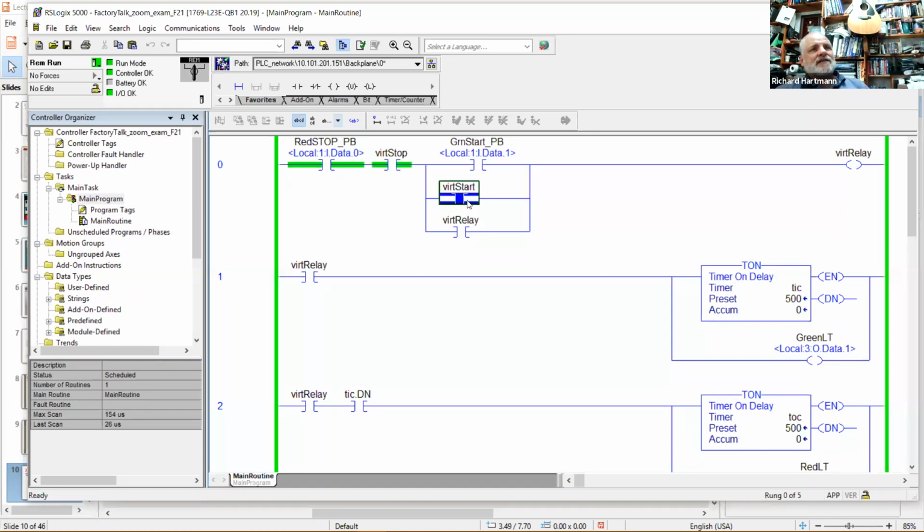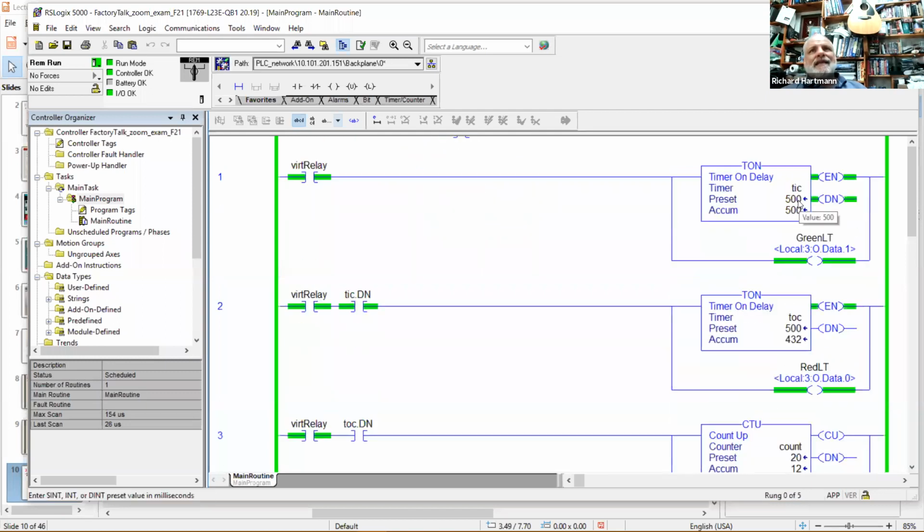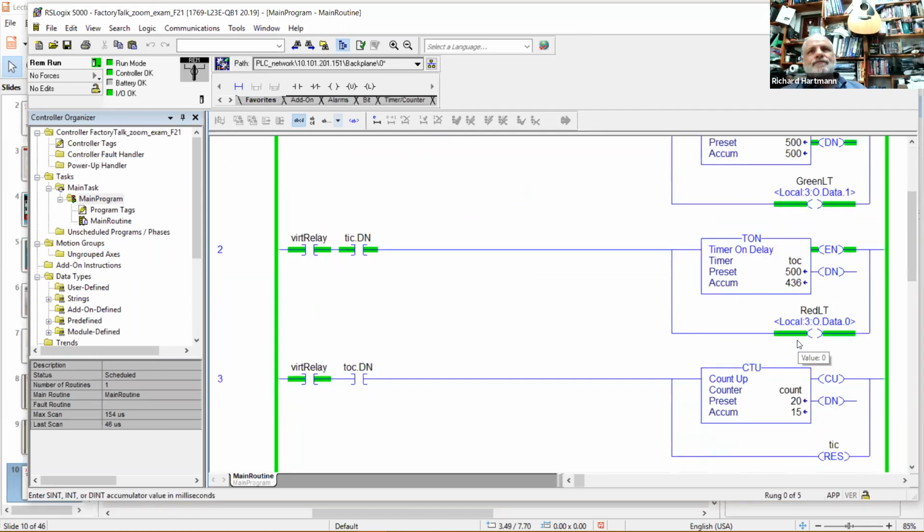And the same thing for this. So I can come to my virtual start, do Control T, and that energizes the relay. And then take that back off once you do it, because your start button only needs to be high for a minute. So meanwhile, you can see now the timer is counting, and my counter is counting up. Now it hits 19. And when it hit 20, it was only 20 for like a microsecond. It was 20 for one scan, and then it got reset.